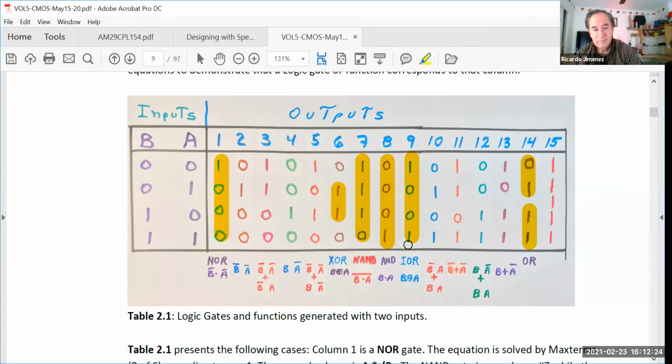So they are equal, okay? And so you have 2 types of gate, the exclusive OR and the IOR. They are very useful in designing arithmetic logic units or designing zero detections in blocks, when you want to detect if a counter, if a loop has ended, you need those types of gates. And also the exclusive OR gate is used to change the polarity.